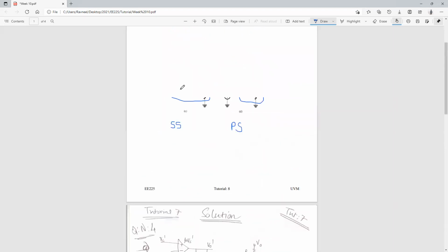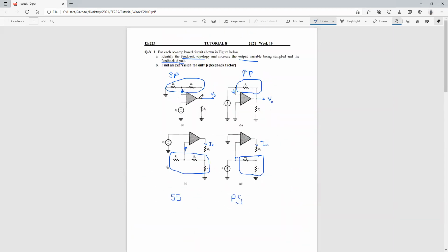So in this situation, for your input resistance for the alpha circuit, or what we say is the open loop circuit, we break this particular point over here, right? If you break this point, this R2 becomes grounded. So your input will be basically your supply voltage, the supply, and we have two resistances in parallel to each other.